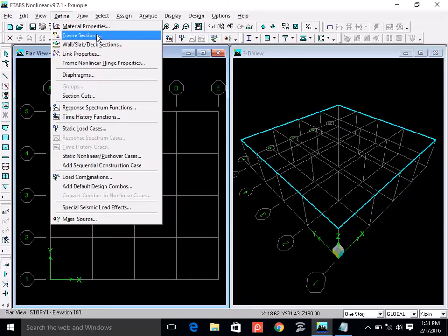When I say a 24 inch deep beam, it doesn't mean that the drop of the beam is 24 inch. It means that the drop of the beam plus the slab thickness is 24 inches. So from the top of the slab to the soffit of the beam is the total depth. So if you want to model this and you don't know the size in the beginning, you can say, okay, it is a 30 feet span, you can begin with 30 inches.